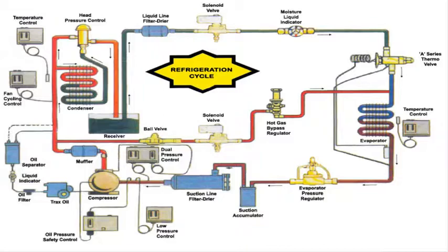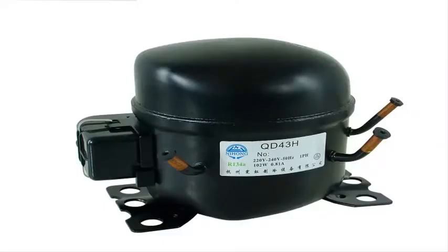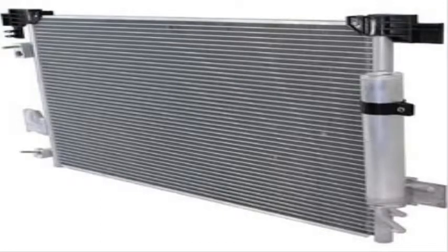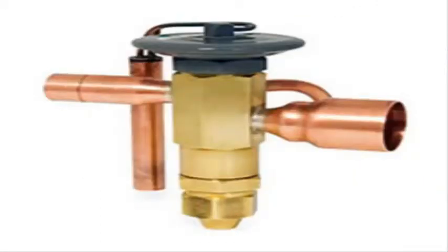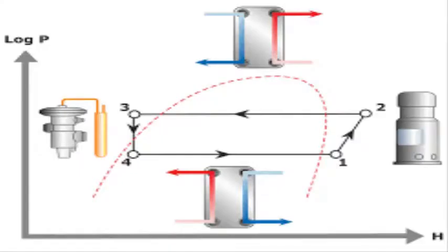Air conditioning is a way to keep our home comfortable by controlling the temperature, air movement, cleanliness, humidity, or dehumidifying for our comfort. To move heat from the evaporator to the condenser we need refrigerant freon and other mechanical components such as compressor, condenser, expansion device, and evaporator. Therefore we need to understand how heat transfers between these components and with ambient.